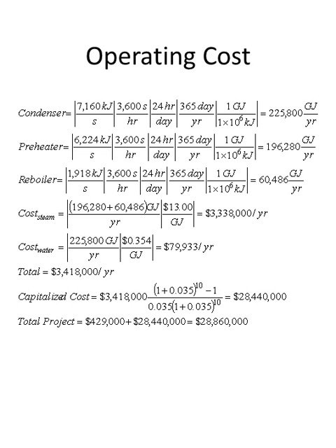The cooling water in our condenser is considerably less expensive, but it calculates to be $79,900 per year. So our total annual utility bill is a little bit more than $3.4 million a year. But we want to capitalize this cost so that we can compare it with the purchase cost of our distillation tower.